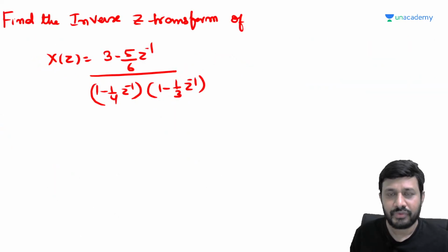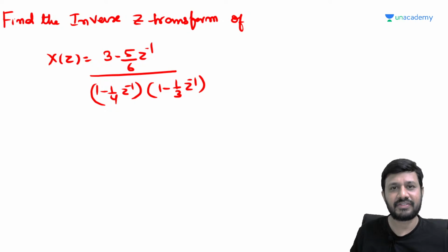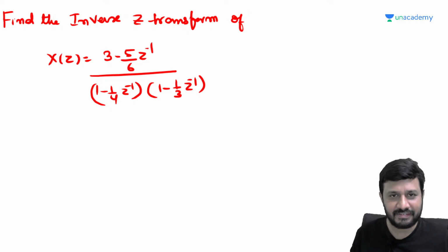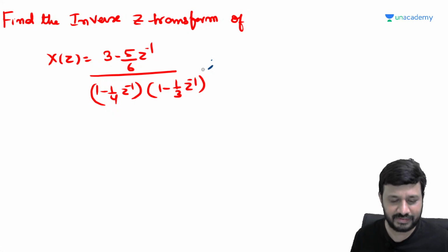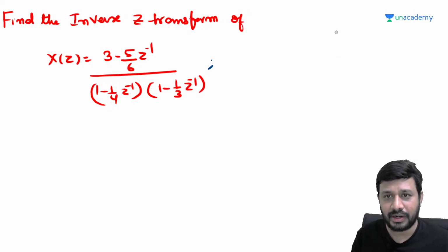And if you remember, day before yesterday we saw the synthesis equation for calculating the inverse Z transform, but we won't be using that synthesis equation. Rather, we'll be finding the inverse Z transform using the partial fraction approach only. Now try to resolve this into partial fractions. And look here, ROC is not given, no? ROC is not given means our job is to consider all the possible cases. For that, how are we going to proceed? First of all, draw the pole-zero plot.